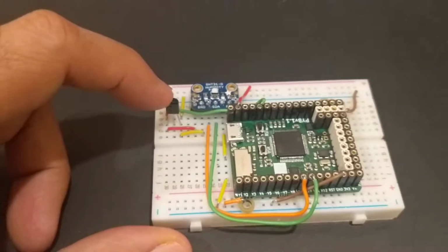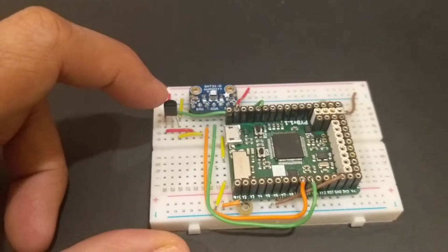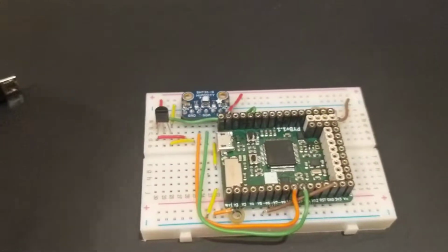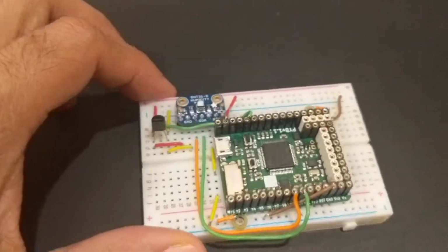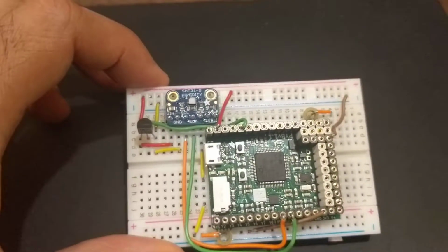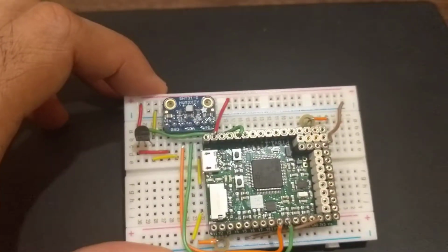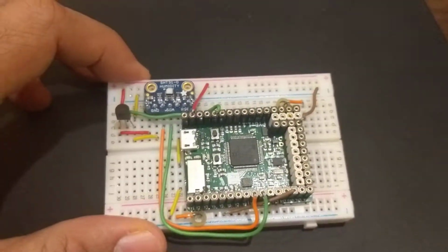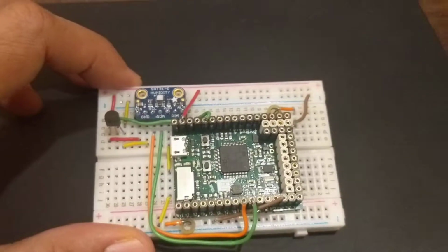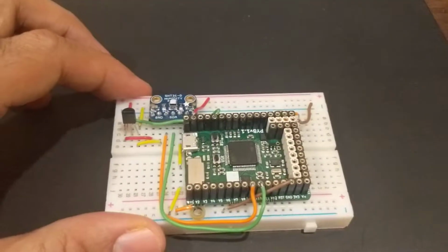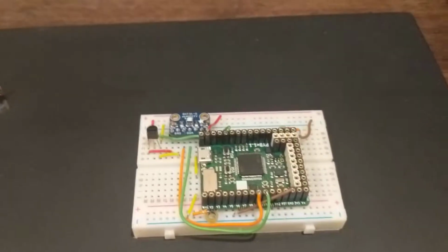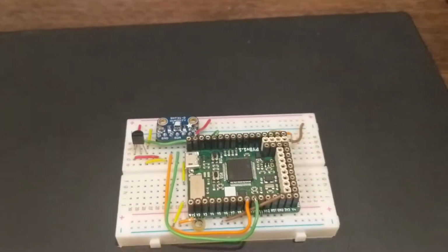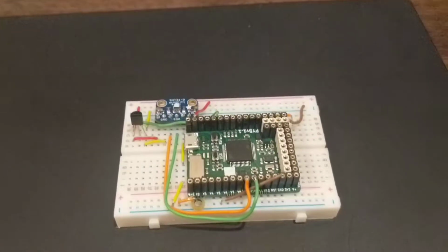and then use that as a reference to calculate the temperature. The Analog Devices sensor voltage varies linearly with temperature. And the other one is an I2C device. We send a specific value as per the data sheet, and we retrieve the sensor output, and we convert that into the temperature value by applying the conversion factor provided in the data sheet.